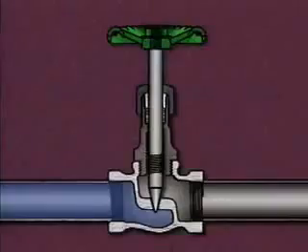Needle valves are generally smaller and longer in relation to their piping than other types of globe valves. As this cutaway illustration shows, a needle valve seat opening has a very narrow diameter. When the valve closes, the disc descends deep into the seating area.